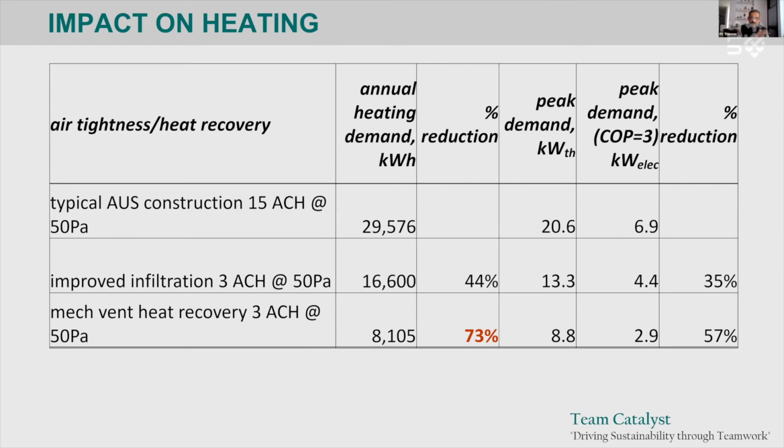Okay, you've got to look at cooling as well. And again, you have to combine what you can do with natural ventilation and what you can't do with natural ventilation. The problem with cooling is, of course, that you need the cooling on the worst day. Okay, so even if you did all the strategies for natural ventilation, if you put the system in, the system's got to handle the worst day.